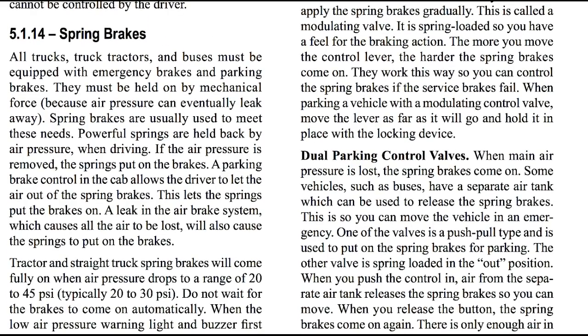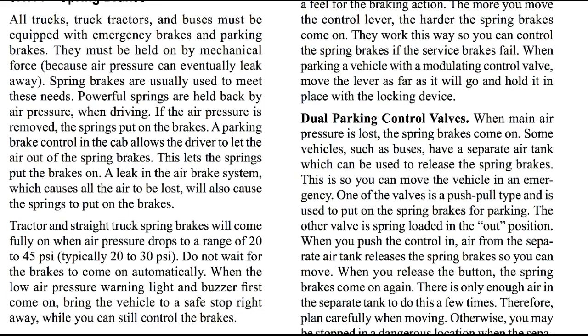Spring brakes. All trucks, truck tractors, and buses must be equipped with emergency brakes and parking brakes. They must be held on by mechanical force because air pressure can eventually leak away. Spring brakes are usually used to meet these needs. Powerful springs are held back by air pressure when driving. If the air pressure is removed, the springs put on the brakes. A parking brake control in the cab allows the driver to let the air out of the spring brakes. This lets the springs put the brakes on.